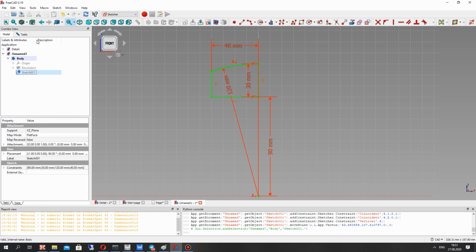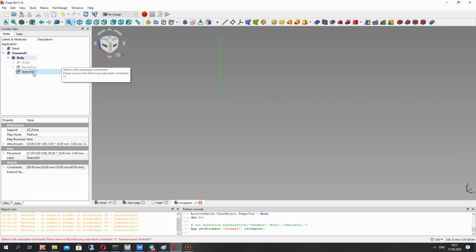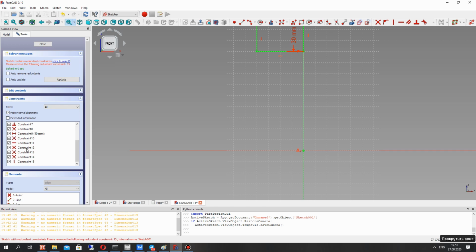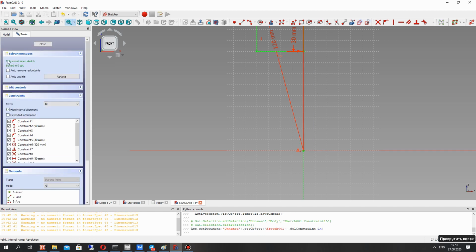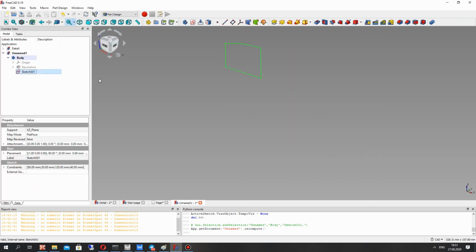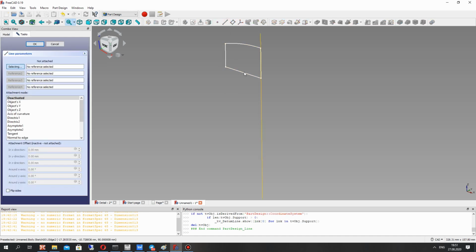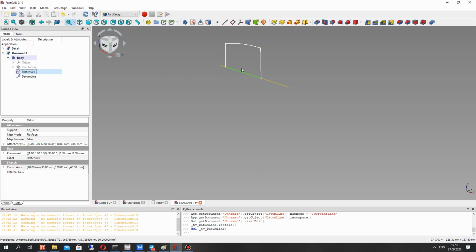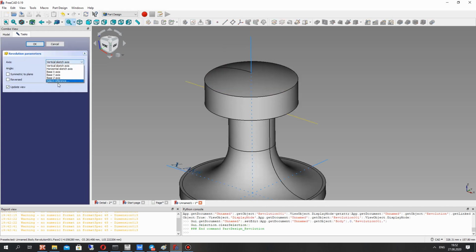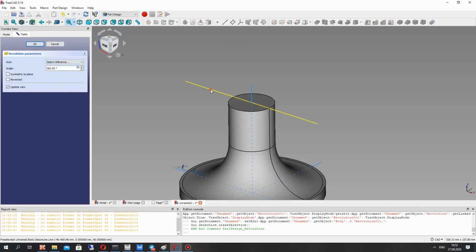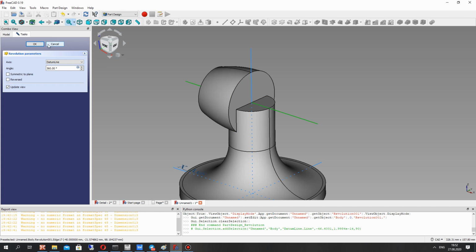If you see the green sketch, we defined all dimensions for the sketch, but we have a false one, and let's delete one dimension and let's make the revolve operation. Let's create the axis for the revolving tool, and choose this axis and click OK.